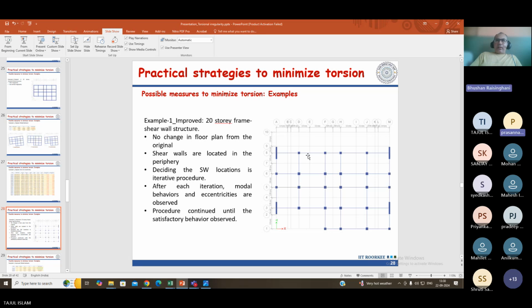No, for design we also have design for torsion in the IS code. But that option is not there for a member. If you right click on the ETABS model, that option is not there. You just see what forces are considered in the shear wall design. It is actually the analysis moments, moment and shear, not the torsion forces.